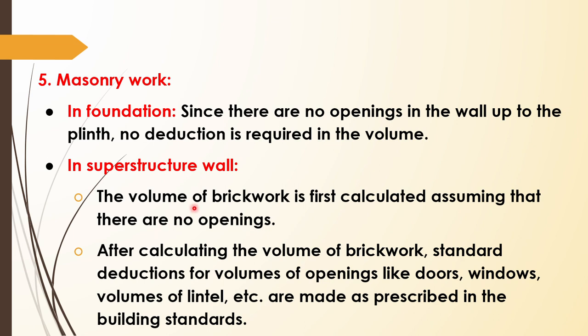Now, if you are moving on to the superstructure, you know that if we are making a wall, we need to provide windows, ventilations, doors, etc. on the walls. So they are holes actually. In that portion, we are not providing any masonry work, right? So we have to deduct that particular area or that particular volume from the entire masonry work.